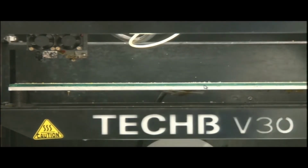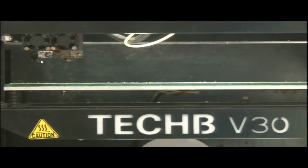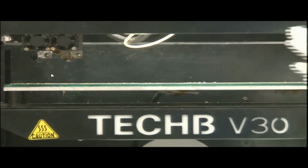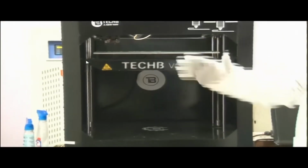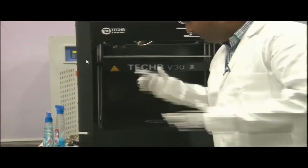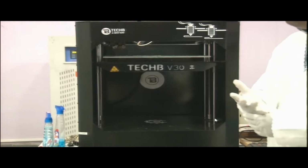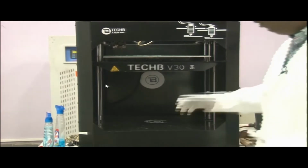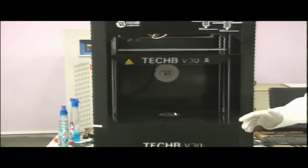It is heated to a specific temperature so that the material deposited here, whose temperature is about 200 degrees, can stick and set easily. We have to deposit one layer upon another during fabrication. In FDM technology, the machine size is 1 foot by 1 foot by 1 foot, so in XYZ directions the envelope is 1 cubic foot.